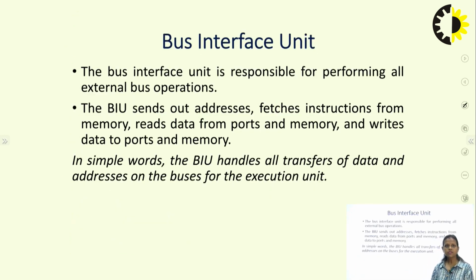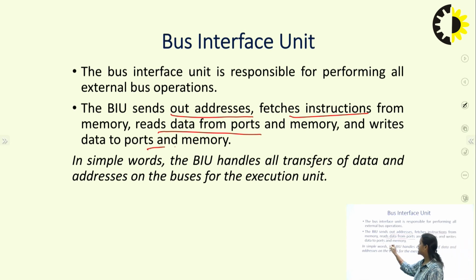So what is the function of the bus interface unit? The bus interface unit is responsible for performing all external bus operations. It sends out addresses, fetches instructions from memory, reads data from ports and memory, and writes data to ports and memory.